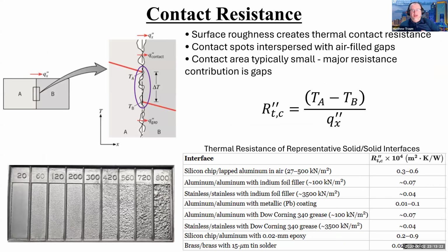So while we are talking about this resistance analogy in heat transfer, the analogy between electrical resistance and thermal resistance, another resistance that I want to mention is called contact resistance. You guys are going to battle this one quite a bit. I think in the heat transfer lab kits, because it'll rear its ugly head at least a few times. But this is a resistance that shows up owing to the surface roughness between two solids that are in physical and thermal contact with each other.